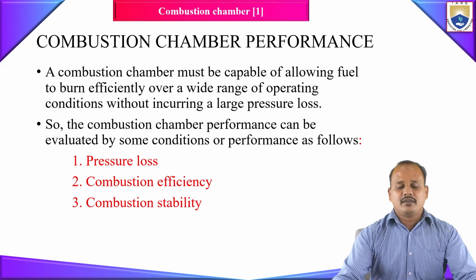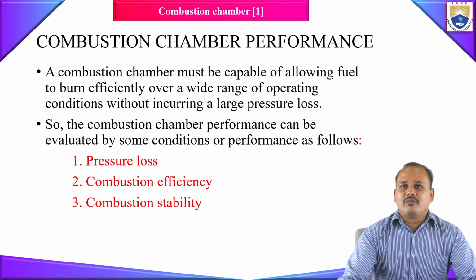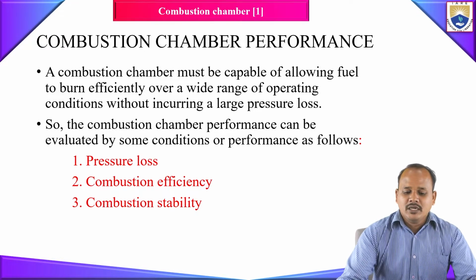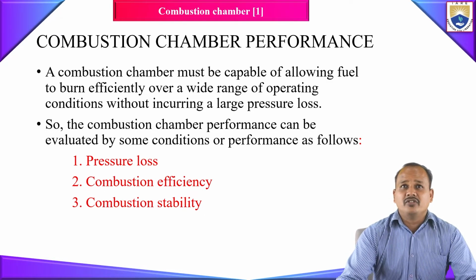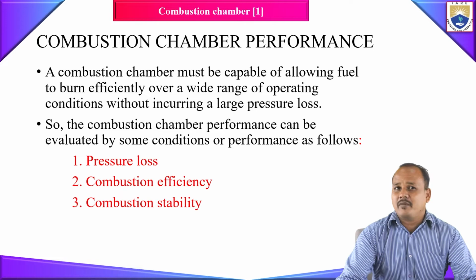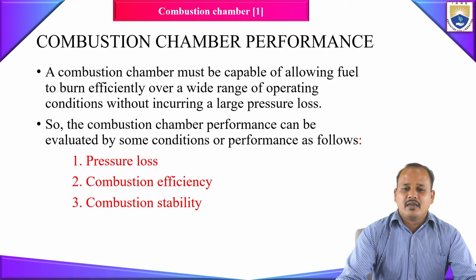So next we are going to discuss the combustion chamber performance. Basically, you know what the purpose of your combustion chamber is? It is to convert the energy stored in your fuel into thermal energy, or to burn your fuel completely for a wide range of operating conditions, irrespective of whatever happens to your inlet condition. For example, if the atmospheric pressure or your aircraft speed is changing, it should complete the combustion process without much total pressure loss.